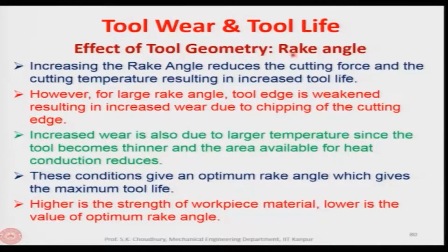Effect of tool geometry, let us say rake angle. Increasing the rake angle, we know, reduces the cutting force and the cutting temperature, therefore resulting in increased tool life. This we have discussed while discussing the selection of the rake angles. So, increasing the rake angle will reduce the force, reduce the cutting temperature, and the tool life will be increased, and vice versa.